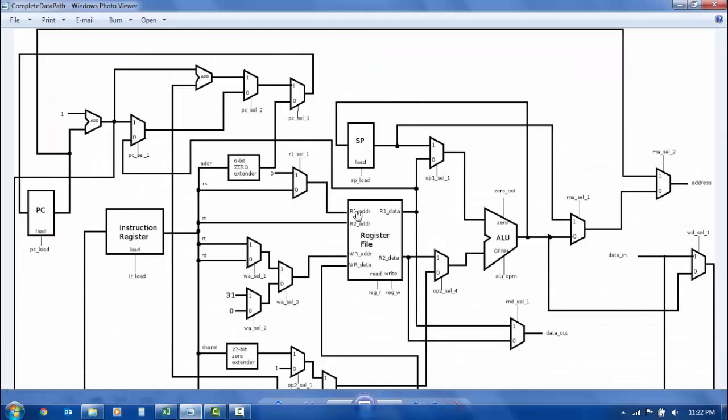If we put both reg r0 and reg w0 at 0 0, it's a hold for the register file, meaning holding the previous read output at the output ports like r1 data and r2 data, and 1 1 is an invalid operation. So let's say we don't use 1 1 at all for reg r and reg w. Similarly for the memory signals, right?